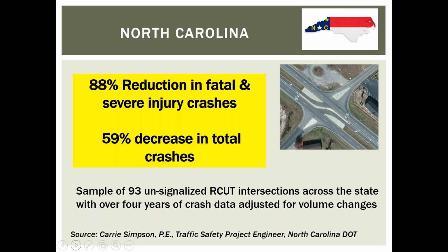So here's some of the safety data that has been collected by states that have implemented a lot of R-CUTs. North Carolina, possibly the most proficient in R-CUTs. This was a study that looked at 93 unsignalized R-CUTs across the state: 59% decrease in total crashes, and 88% reduction in fatal and severe injury crashes. That is amazing.